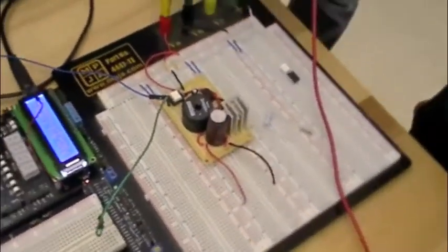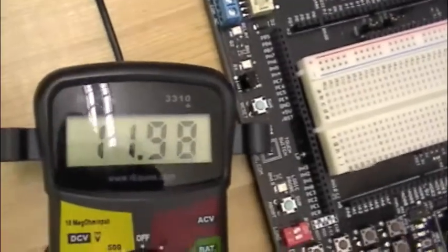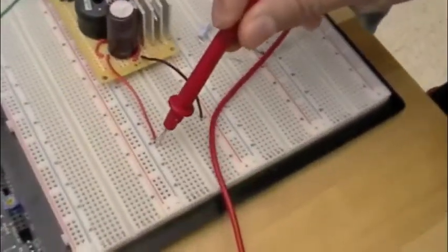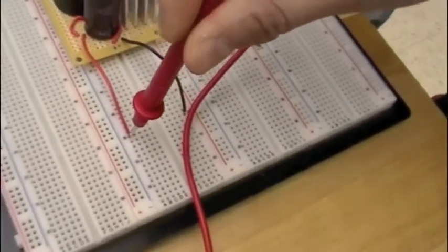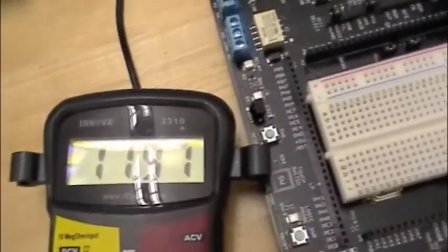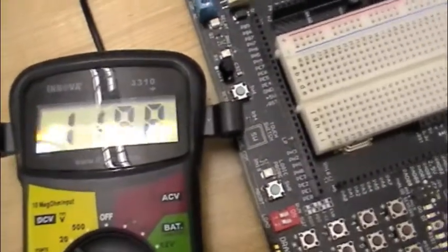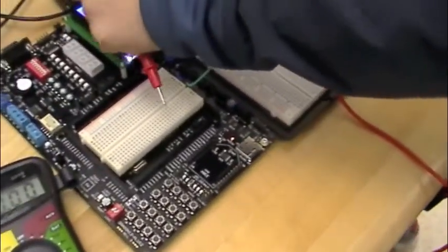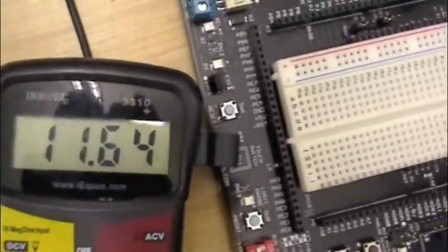Alright, now we're going to show you guys the functionality of our buck converter. Right now we have an input of 11.98 volts, and on our output, since our output's in parallel with our input, we get just about the same thing. And then when we apply PWM to our circuit, the transistor is going to conduct a little bit, and we're measuring our output, so it's going to sag. We're going to have some slight losses across our capacitor, inductor, and transistor just due to the leakage current.